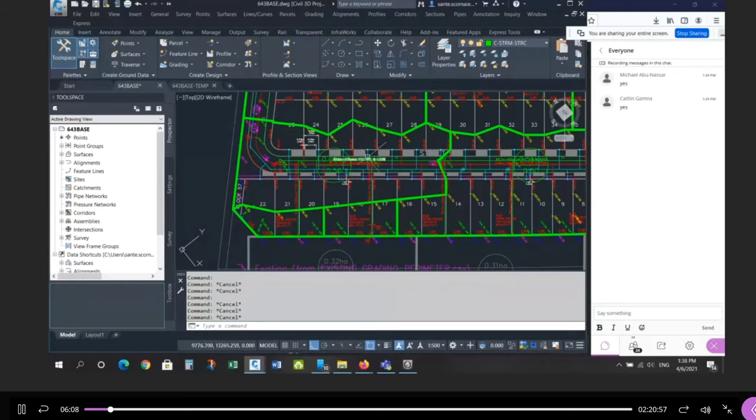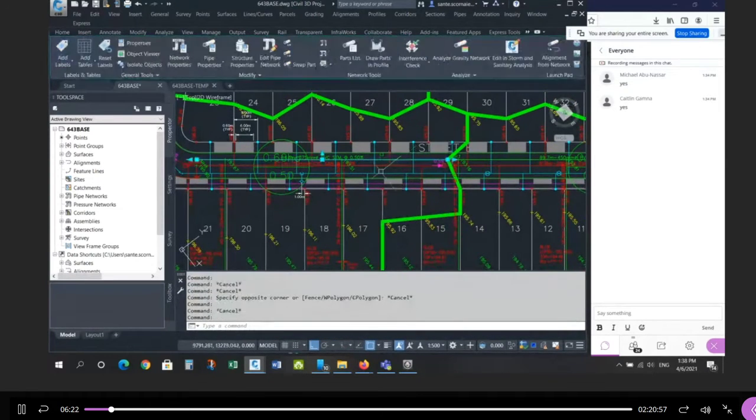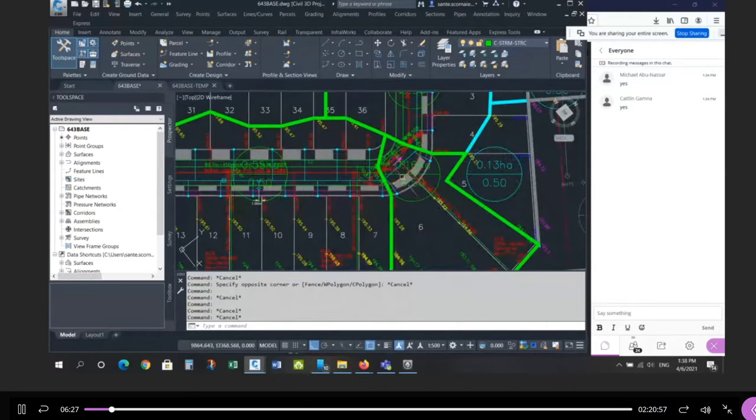So I know these backyards now are coming toward this street. So I got rid of this, this, and this. Whoops, sorry, this and this. So these three areas now combine to become this one area, the total tributary area that gets into this street sewer, this storm sewer. So I did that here, I did that here, and I did that here as well.